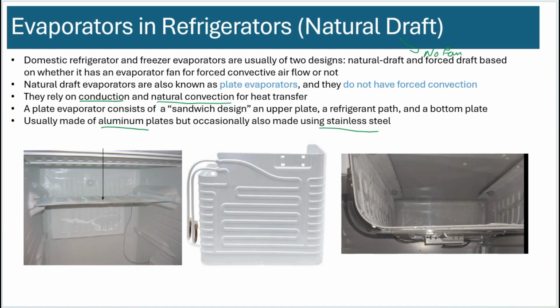So you can see there are some projections here. So the refrigerant goes in this sandwich, inside the sandwich between these two plates. And you can see at the end, they're connected to tubes, two tubes, okay? So one is inlet and one is outlet. So it's going everywhere in the plate and providing cooling throughout the plate.